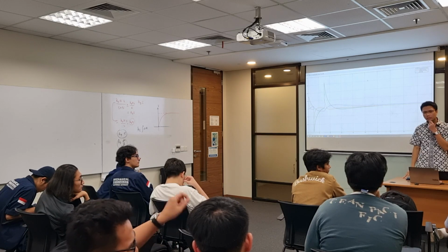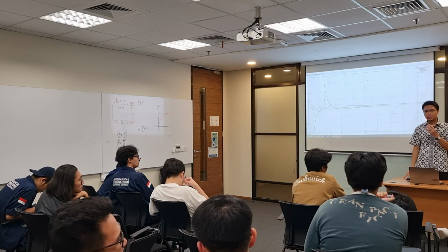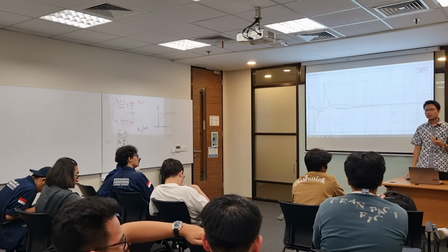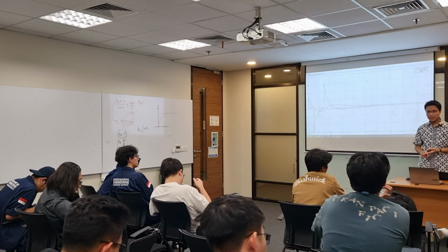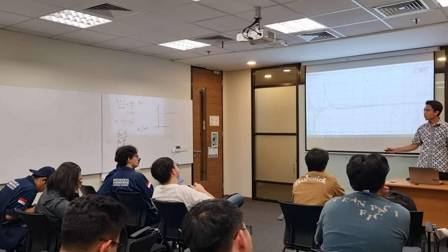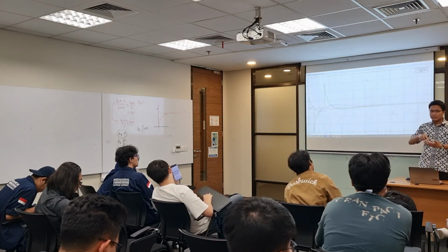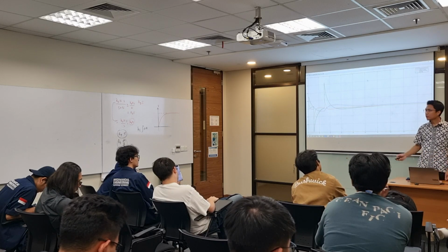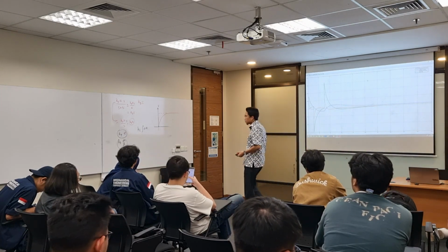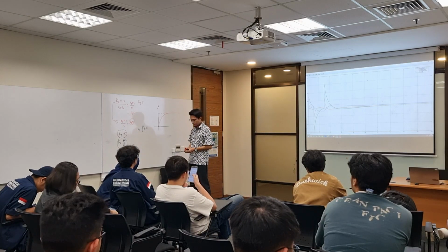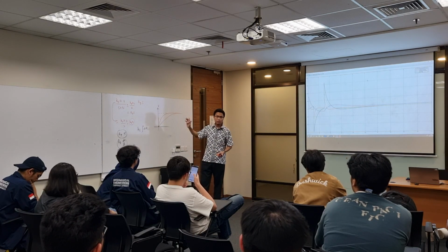I was wondering whether we need all three of them. Not in all situations do we need the three. Usually PI control is sufficient. The D part you need when your input has a sudden change. If your input is very slow, listen to me, if your input is very slow like this, then you don't need derivative control.